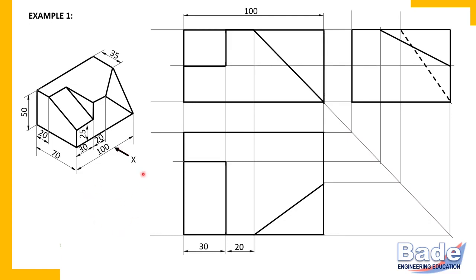Okay. Now focus on width dimension or height dimensions. Okay. 25 height. So I measured 25 height and 50. Okay. Here I told you this is chain dimensioning or dimensions in series. Here dimensions are parallel dimensioning. When you insert dimensions, lines or dimensions parallel to each other, remember smaller dimensions must be closer to the boundary of the view. Distance between boundary of the view and parallel lines must be sufficient, at least 8 millimeters.